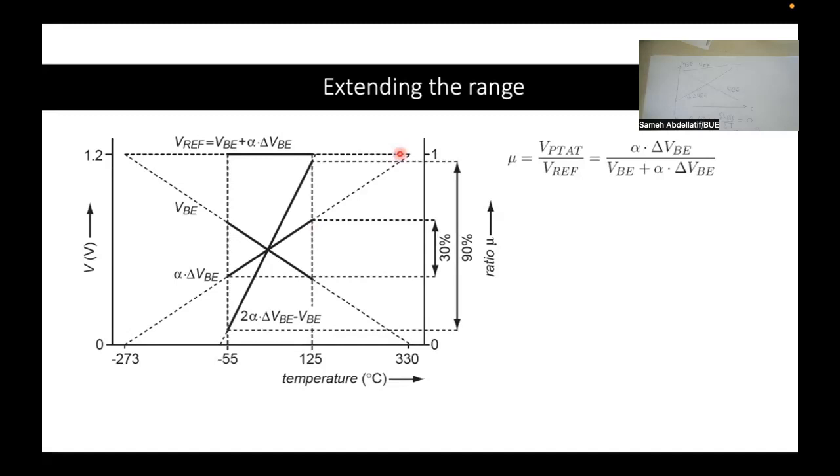So one of the proposals in this direction is to efficiently utilize your scale. One of these solutions is simply, as you can see from this graph, to change the slope. As you can see here, we double the slope of the numerator and we fix the denominator. So V reference is still the same. It's not allowed to touch V reference, because this V reference should keep a constant parameter.